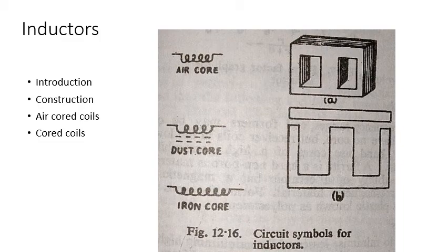We know that an inductor is what? An inductor is a core with a number of turns wound over it. So an inductor is always arranged as a coil of wire. The choice of core for the coil is governed by the order of frequency of current the coil is expected to carry. For very high radio frequencies the core is simply air. Lower radio frequency inductors use a magnetic dust or ferrite core. Low frequency AC coils are inductors for smoothing of ripples in the DC output of a power unit and have a laminated core.